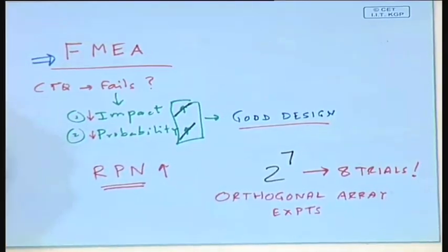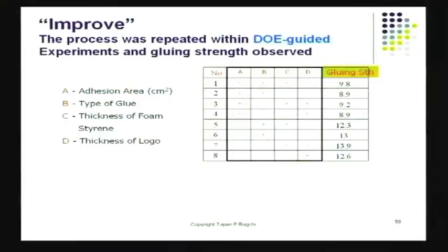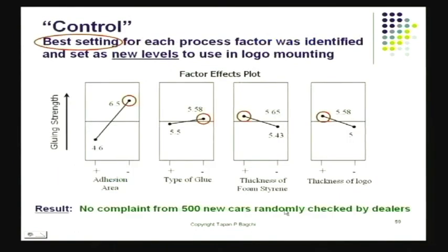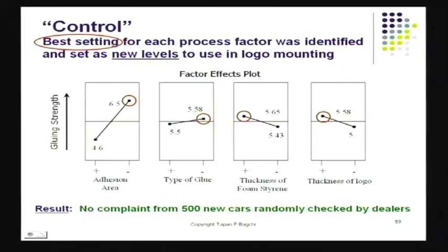And that's what we see when we look at the matrix here. This matrix here is an orthogonal array. And this is good enough for me to calculate my factor effects and to plot these effects there. Of course, I'm not really reaching the ultimate optimum, because that would be one of those 2 to the power 7 combinations that are possible. I just don't have the resources for that. But just see what this simple method has done for me. It has cut down the number of trials from 2 to the power 7 to 8 only, and I've been able to find a pretty decent practical answer.